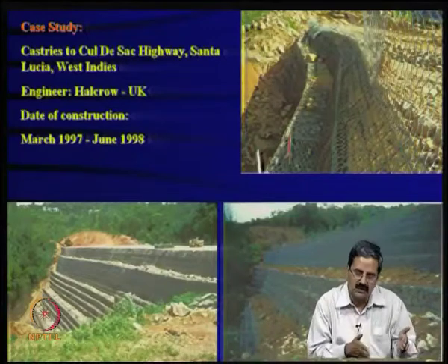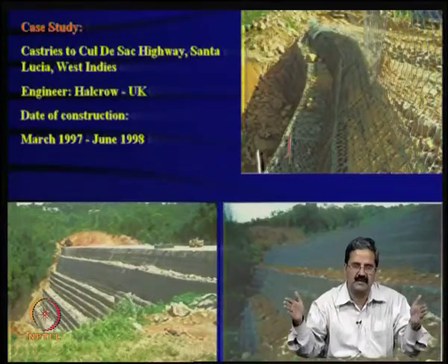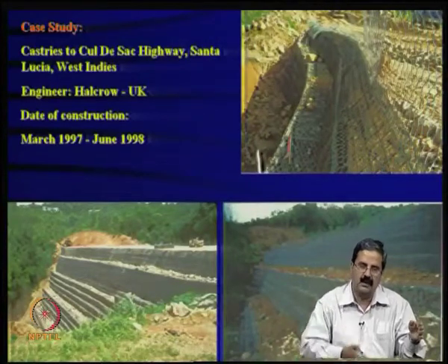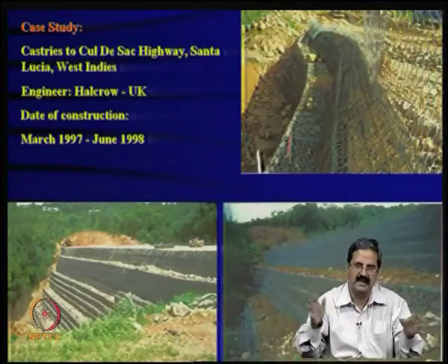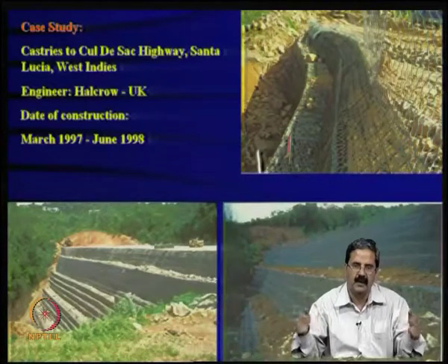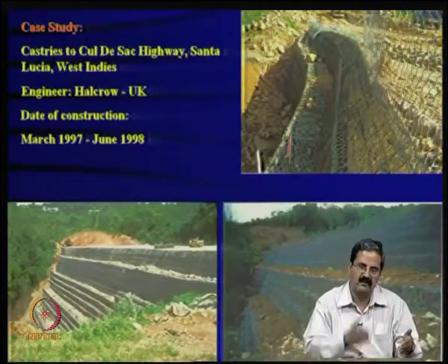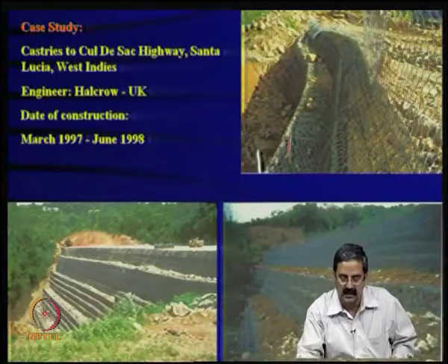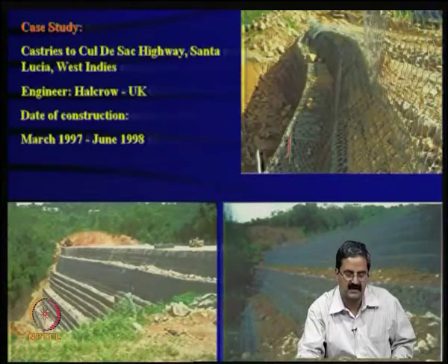You have to start from the bottom, and suppose you want to increase it to say 10 meters, you can identify the area, find out the backfill material, try to give a design, and it is possible. That is very important. And this can be done with any type of facing, any type of materials can be used.